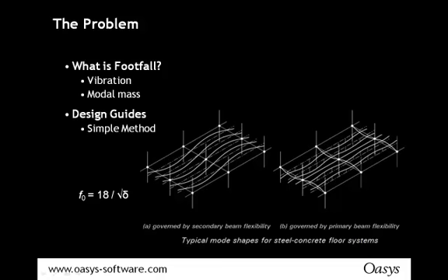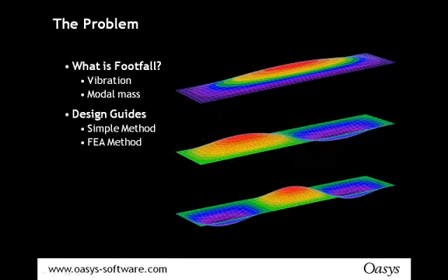So both the Concrete Centre and the Steel Construction Institute recommend that you should actually use the FEA method, so do a finite element analysis of your structural floor to get accurate results and accurate predictions of how the structure is going to work.